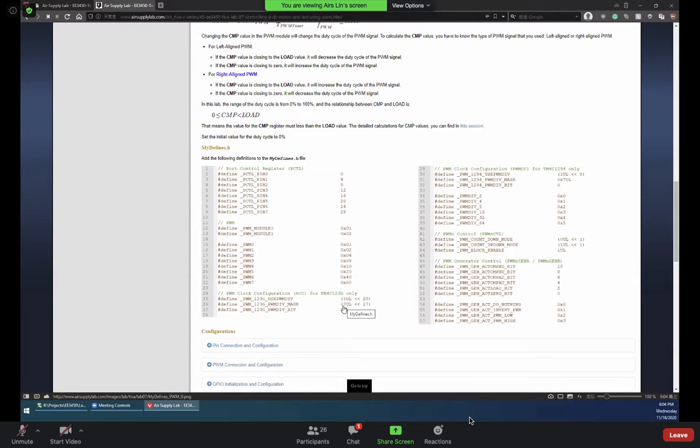Okay, so 3-bit 111 should be the 7, not the 3. Previously I put the 3, which is just 2-bit. So that's why when you configure, you get the incorrect result, especially for the servo. If with the servo you cannot get exactly the frequency and the pulse width, then you are not driving your servo.